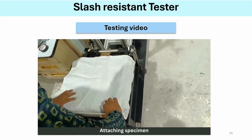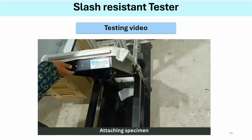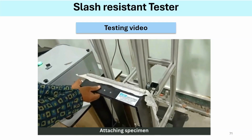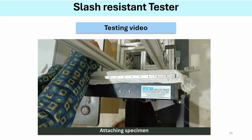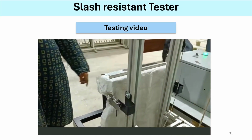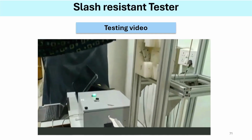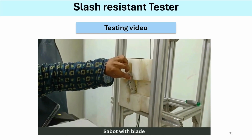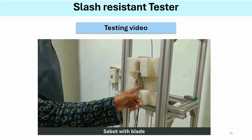Any wrinkles and folds are being removed, and the lower portion of the fabric is kept free to simulate the exact running condition, and the angle of the fabric holder is kept at 2 degrees inclination.